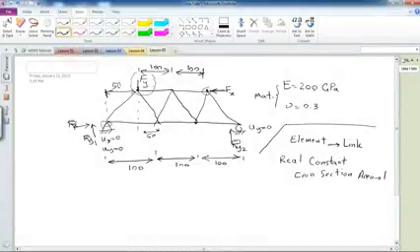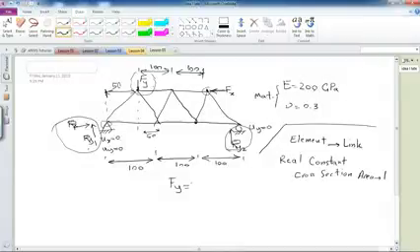And then we're going to find the reaction forces here and here, and we're also going to see the deformation of the truss according to the loads that we're applying here. Let's say the Fy that I'm going to apply is equal to 200, and the Fx that I'm going to apply is equal to 50. And then go through and analyze this model. Okay, let's switch to ANSYS.